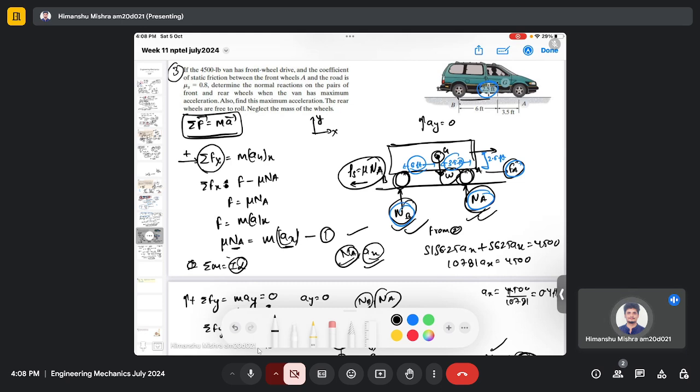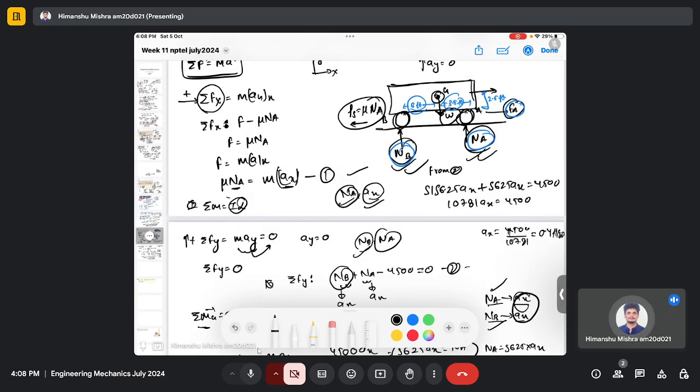First we made the free body diagram and identified the unknowns and the overall number of forces which are acting. From the force balance equations, we found that we have more unknowns than equations. We wrote down the two equations from force balance and found there are three unknowns, NA, NB and AX. So we need a moment equation.